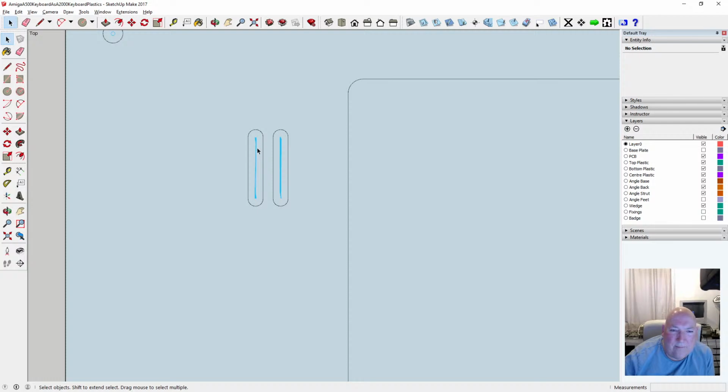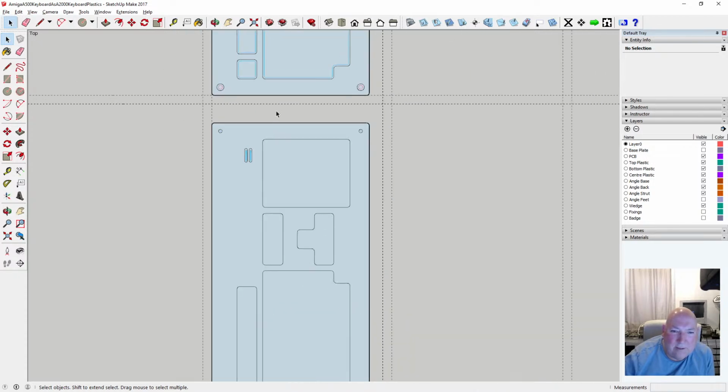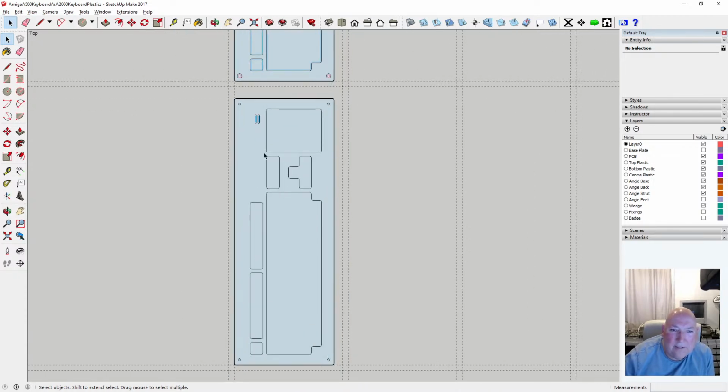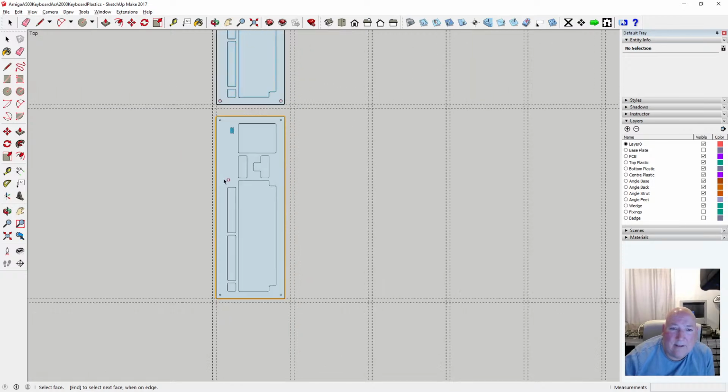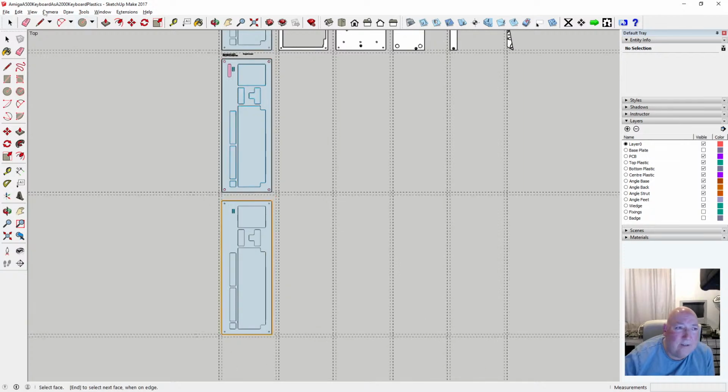Now, those holes, I've made them the size of the LEDs, but my milling bit is bigger than the hole. So that might cause an issue. We'll have a look. So we can do an outside cut on that now as well. Okay, so we've got basically two lots of G code for the same panel. So we'll put it through an emulator now.